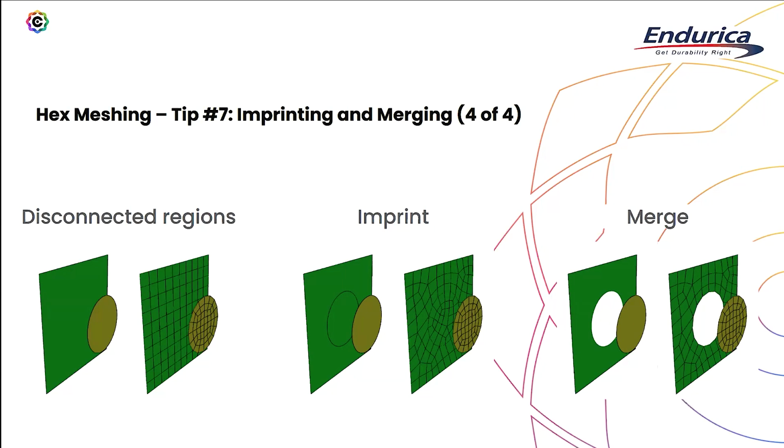That merge operation gets rid of that duplication, and now you can see I really only have two surfaces. So I mesh the circle, and that is now shared on its boundary by both the cylinder volume and the cube volume that we have. Those are the operations that happened. Really getting good at understanding how imprinting and merging happen, and even how those interplay with compositing, is a key thing to understand with Coreform Cubit.